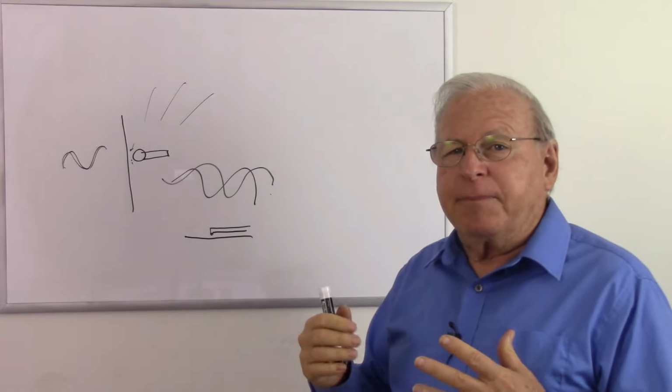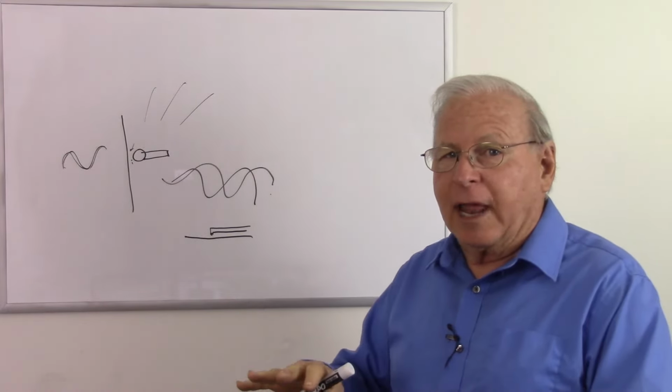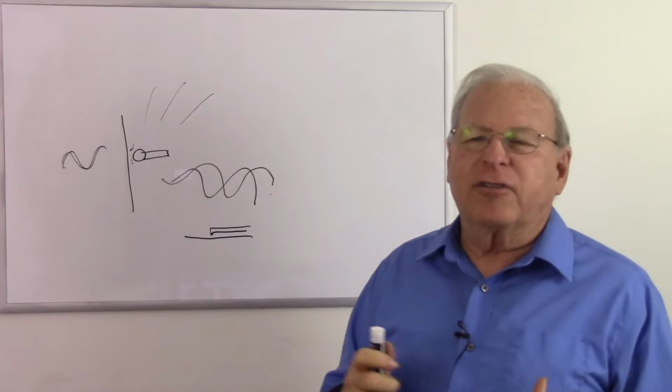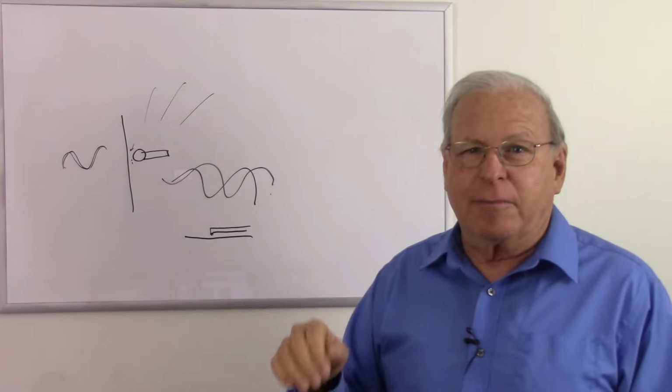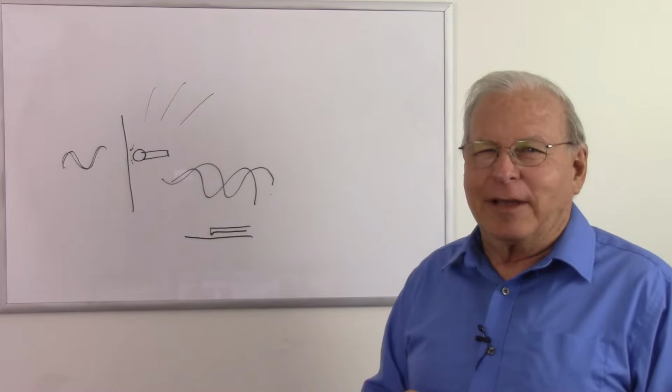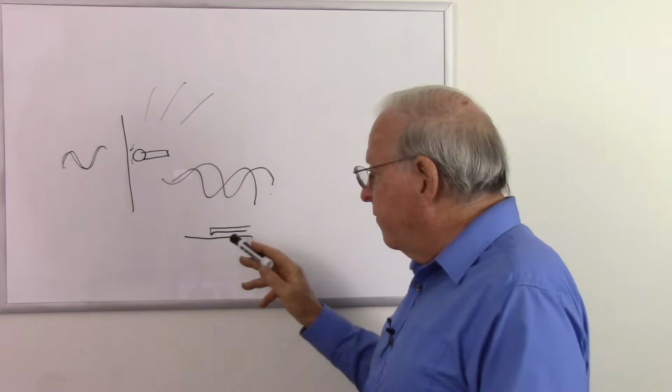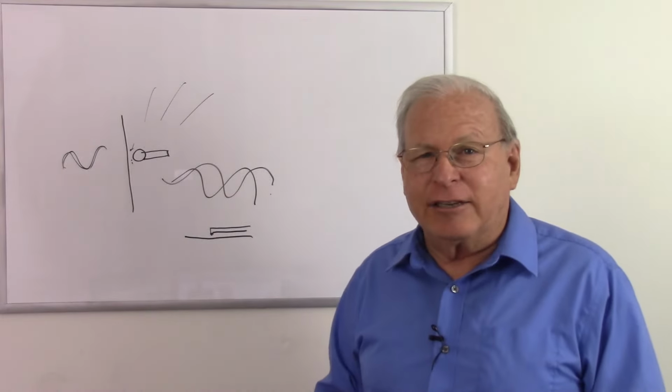Or if they want to pick up the sound of feet on the floor, like dancers or marchers, they might put these on the floor. And in fact, that's a disadvantage of them. If you have this on the table and somebody starts tapping their fingers on the table, guess what you're going to hear in the microphone? So they can pick up unwanted sounds from the surface that they are attached to.